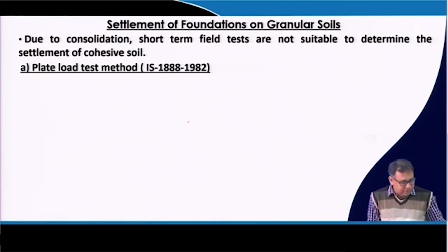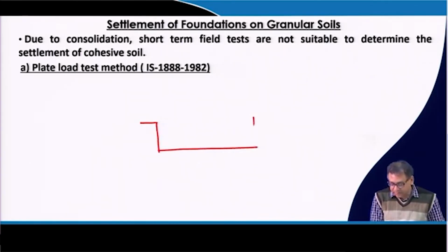So, the plate load test, what is the plate load test? It should be done at the base of the foundation. That means the depth of the plate should be equal to the depth of the foundation. So, suppose we have a test pit, so this is the test pit.